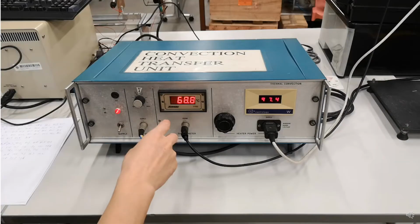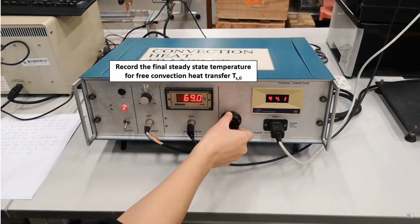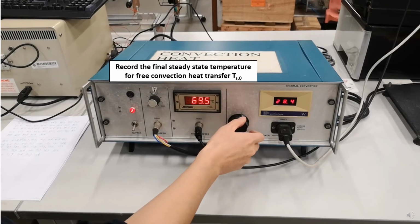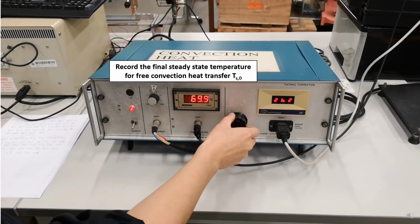Well, when the surface temperature reaches the final temperature we want, we need to turn the power down to 20 volts. Here I just demonstrate how to operate the equipment, so the temperature here is not very accurate. Well, then we need to wait sufficient time until we obtain the steady state temperature, and we need to record this final steady state temperature Ts0.